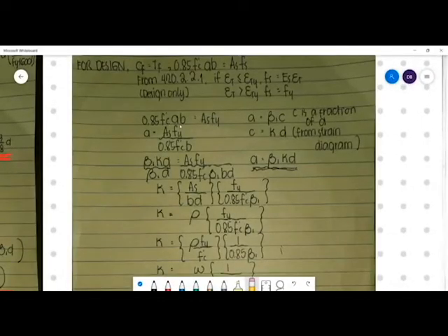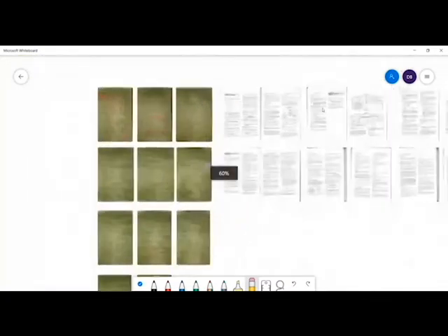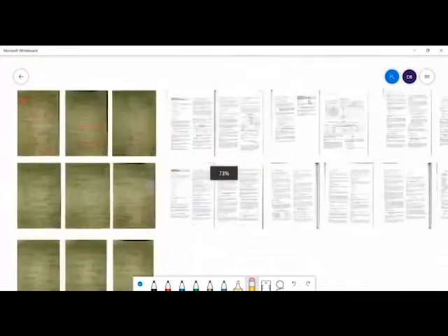After the analysis, we are now going to proceed with the design. So from what we've derived, C_f is equal to T_f, 0.85 f'c a b is equal to A_s f_y. And from your NSCP, what should be the values that we're going to follow? From section 420.2.2.1, let's look at the code again. So section 420.